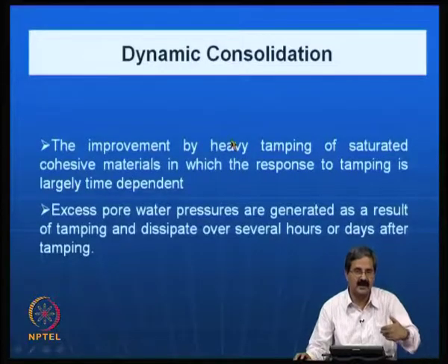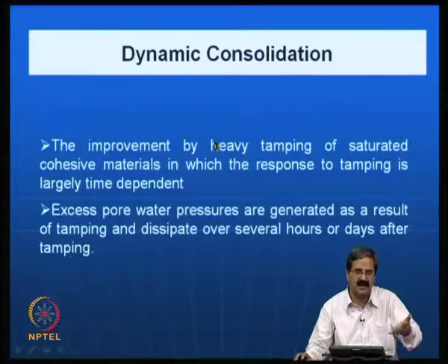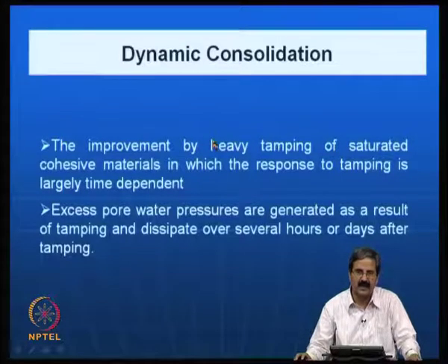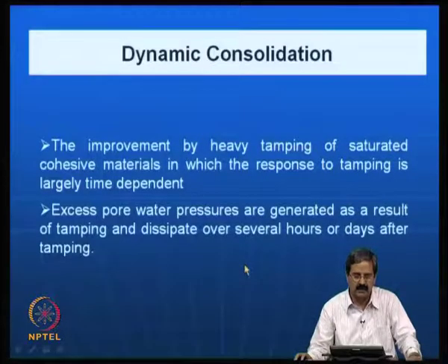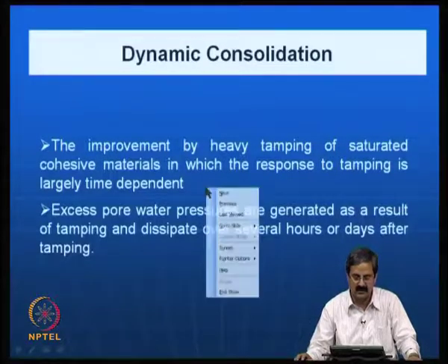Once you get that material and reclaim, you must be able to construct the infrastructure very fast using a proper ground improvement technique. If you have sandy soil which is very loose and you want to construct something on it, you should go for dynamic compaction, whereas if you have clay, you should go for dynamic consolidation.